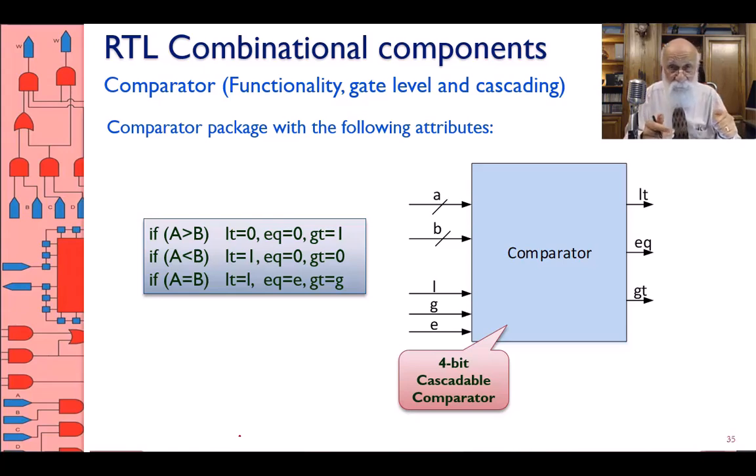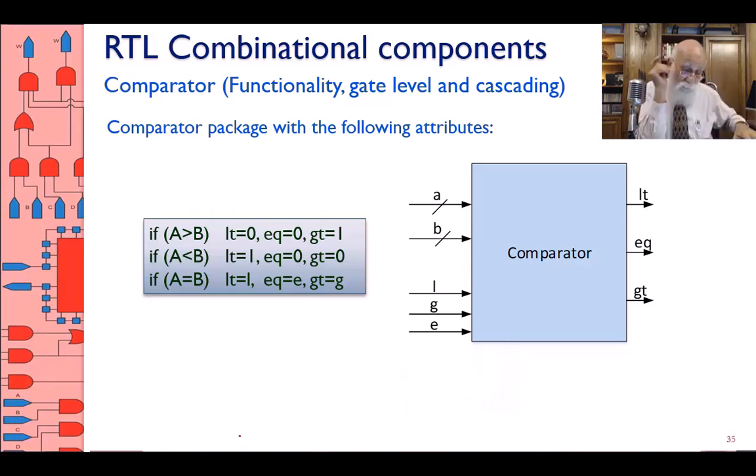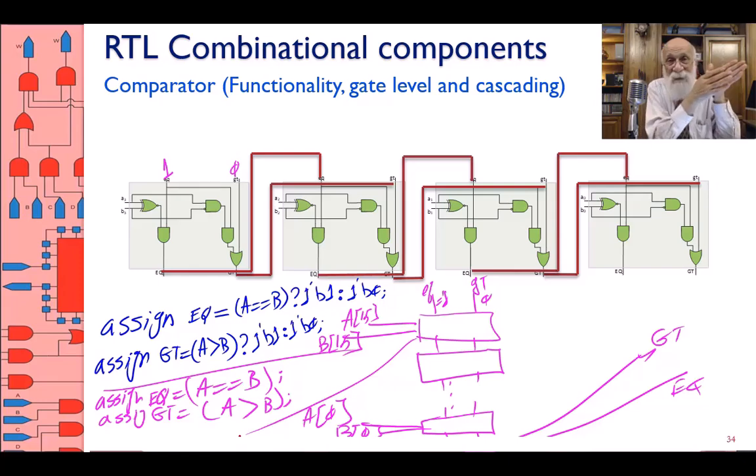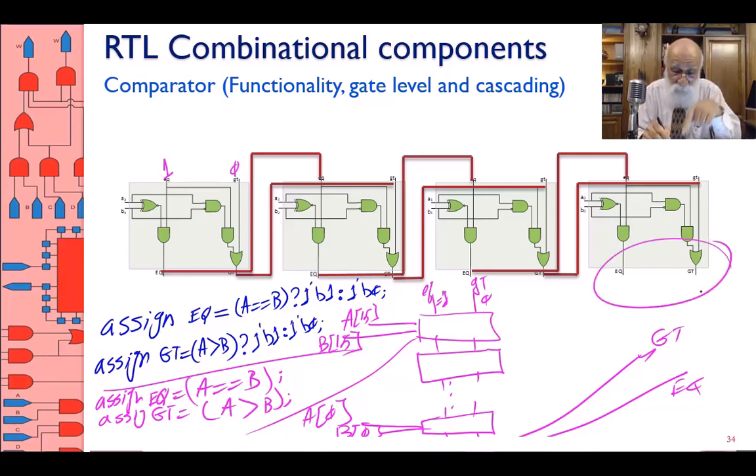Another comparator works differently. We started with the most significant bit in the previous comparator and then went to the right hand side, and the result comes out of the right hand side. What is happening here? The left hand side makes a decision and then propagates the decision to the right hand side. You eventually get your result from this right hand side.